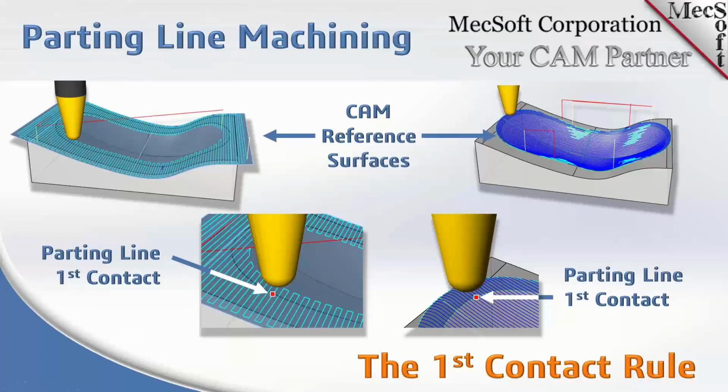So the final technique I guess we're going to get across is what I'm calling the first contact rule for machining parting lines, cavities, and parting surfaces. If you consider yourself the tool and you're running along this parting surface and you hit that parting line, the first contact rule states that you will not touch that same point on that parting line again in the same operation.